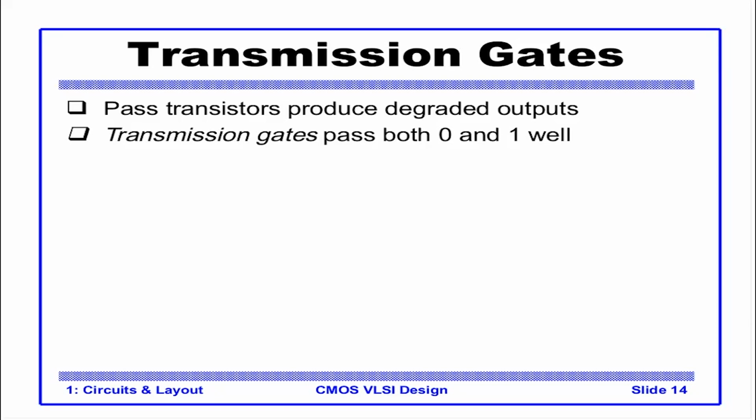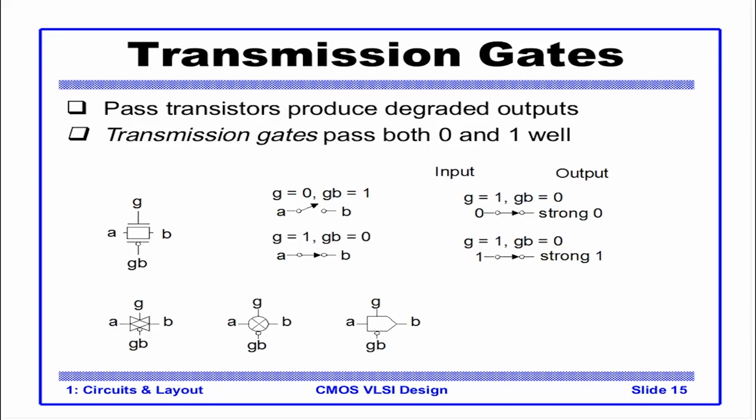Now here, while construction of transmission gate, we connect a PMOS circuit here and an NMOS circuit here. We connect both the sources and both the drains together. This was not the case in static CMOS. Please note, here the input is not coming from the gate. The input is coming from the source side and going to B. B is the output. Now let's see how this functions.